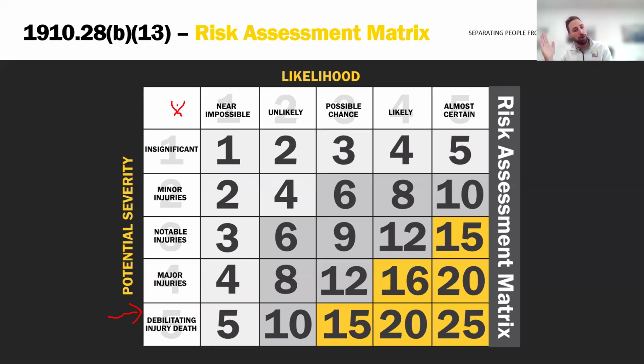Apply it to rooftop fall protection, and we're exponentially higher. Falls occur at 32 feet per second squared. So what that means, if I were to fall or trip backwards off of a 90-foot tall building, that fall is done in under 3 seconds. I do not have time to react, to pivot my body, to land on my feet or tuck and roll. So we're always at a 5.